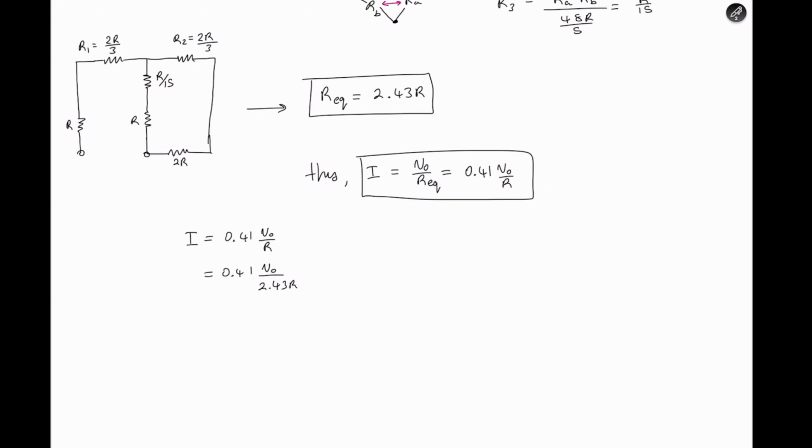So it just comes down to, as a circuit analyzer, which tool is best fit for the task at hand. For the task at hand, we didn't have any current sources, so we see that we have a bunch of resistors and a voltage source. So node voltage is the best method in this case.